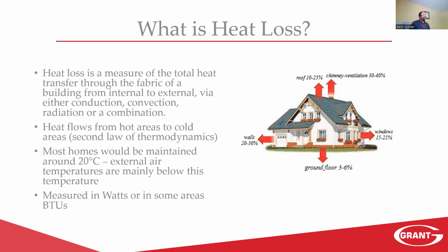Most homes will be maintained at around 20 degrees approximately. The average air temperature externally will be well below this. This leads to a change in temperature, which means you're going to have heat transfer from inside to outside. Heat transfer or heat loss is then measured in watts, or more commonly kilowatts, and in the older terminology, BTUs, which would be British thermal units.